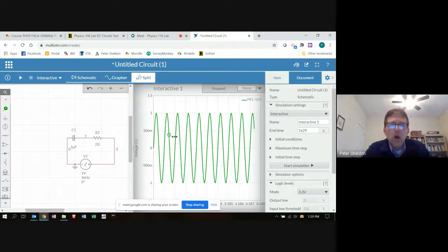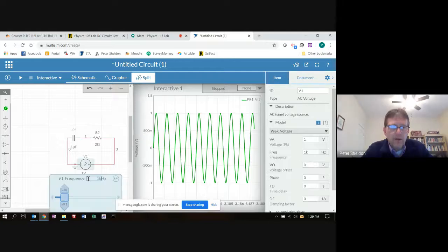So we're not going to go ahead and measure the period. We're just going to turn up the frequency of the generator. At some point, the RC circuit can't keep up, right? So I'm going to turn up the frequency, let's say by a factor of 10. Let me think about it. If it's 2 microseconds, then it's about 5,000 hertz or 50,000 hertz. I'm not sure which. Let's just go up to 50,000. Let's go to 1,000,000 hertz.